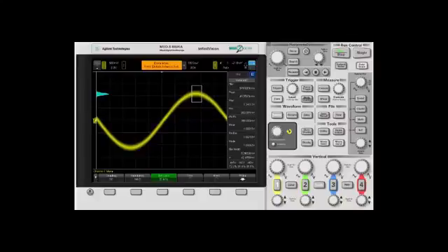but when working with smaller amplitude signals, such as 100 millivolts peak-to-peak, a 2 millivolt peak-to-peak reduction in the noise power is a 2% improvement in the accuracy of the amplitude measurement, which is very significant.